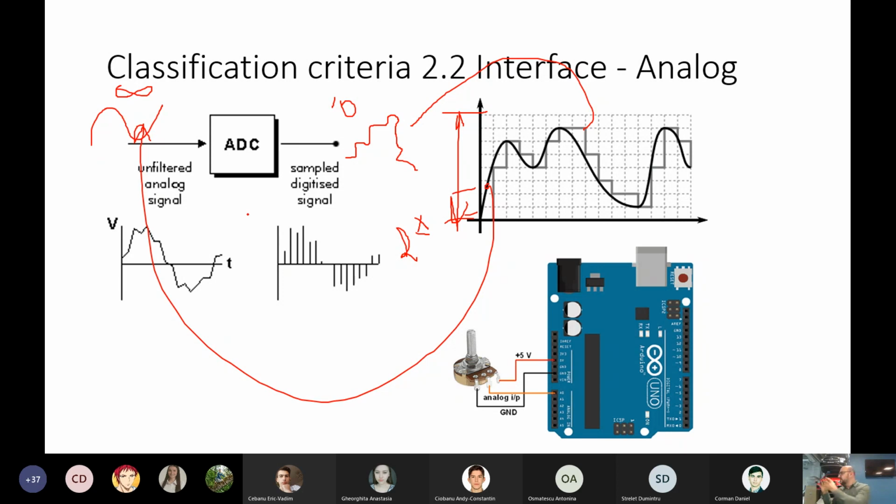And the next iteration is gathering information and providing it to the output. And meanwhile, something could happen. Let's say in this point, we can have a kind of peak, and we will never see that. So we can gather information only at certain points, and we say that we will have time resolution. And time resolution will say how many samples we can have per second.